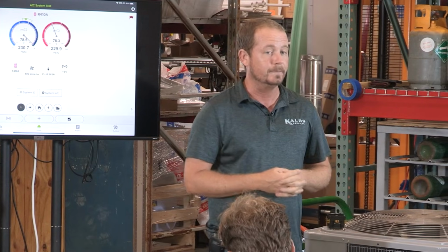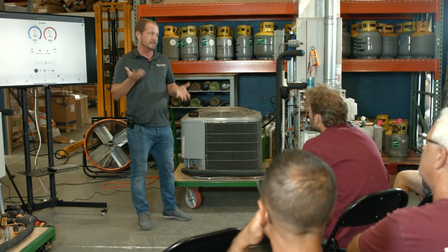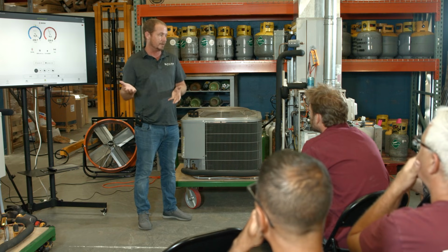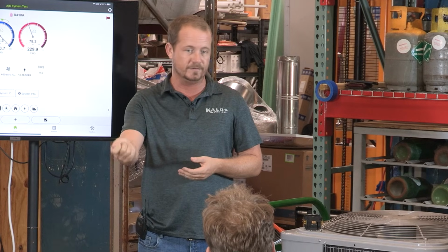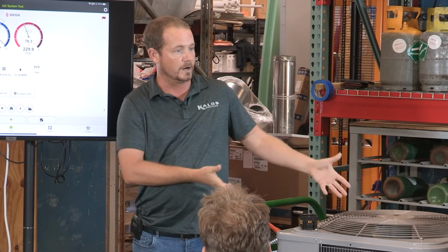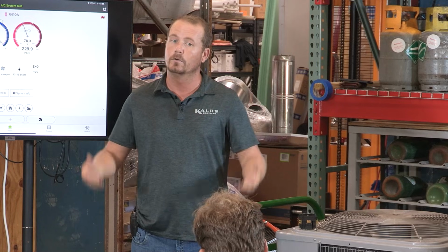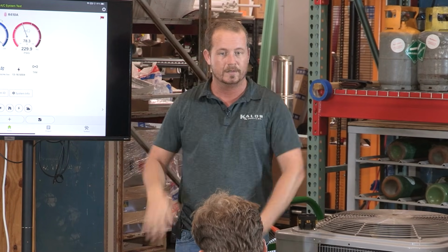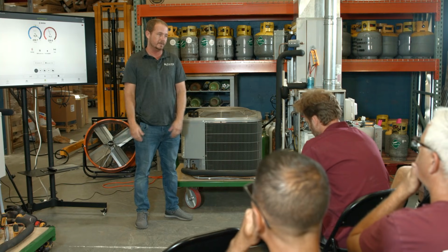And so obviously that will cause low system airflow. It's not that it's ineffective at balancing, because you can actually improve air balancing in a house doing that. But along the way, what are you doing to your supply static pressure? Raising it, right? It's just like crimping the end of a hose. If you pinch the end of the hose, you're building up more static pressure in the hose itself. So rather than that energy going towards flow, it's backing up and building up pressure that's forcing against the blower, and it's reducing the amount of air that can go into the space.